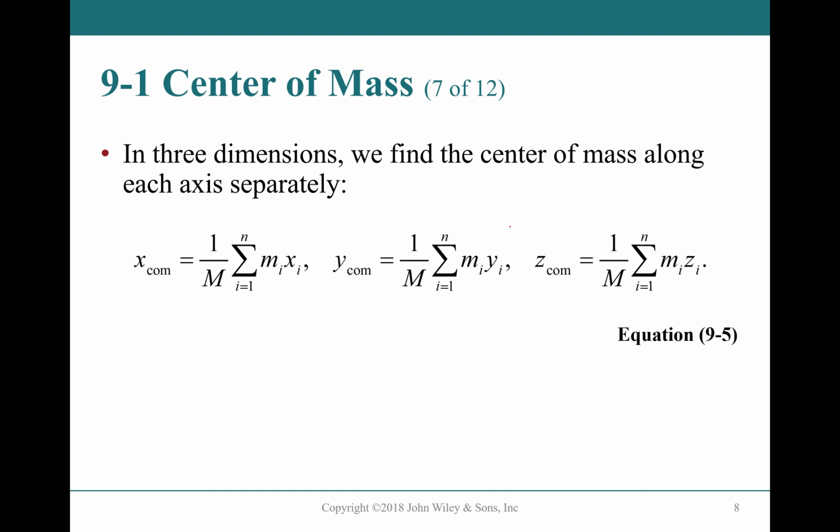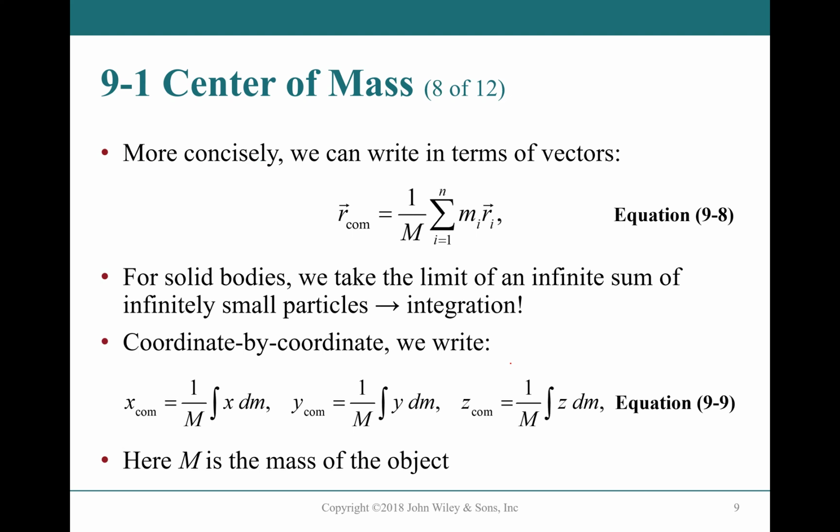And in 3 dimensions, we are going to have x calculated this way, y calculated this way, z calculated this way. So what is this? This is the same as m1 y1 plus m2 y2, and keep on going, okay? And then divided by total m. And also your z will be the same. Find the z coordinate for the masses and divide by the total m.